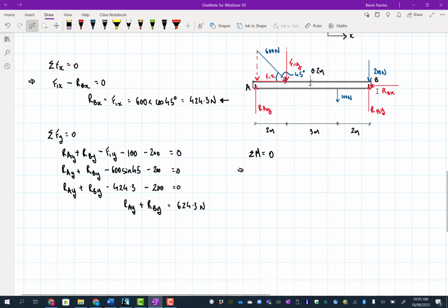So say I take these ones. These two have no moment. This one has a big moment. It's got this force times the lever arm, the perpendicular distance of the line of action to the point you're thinking about. We know these. It's going to have a moment, a small one, because the F1x, its perpendicular distance is only 0.2. And then we've got F1y, it's got a moment as well. This one here has a moment. And so we calculate all those, this one doesn't. So therefore, we could figure out the answer.